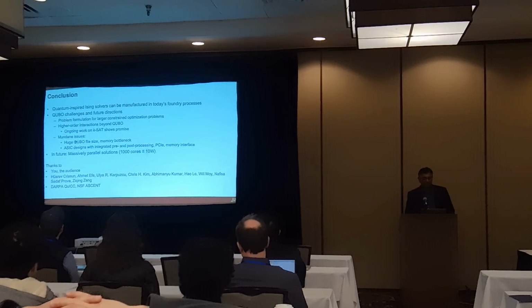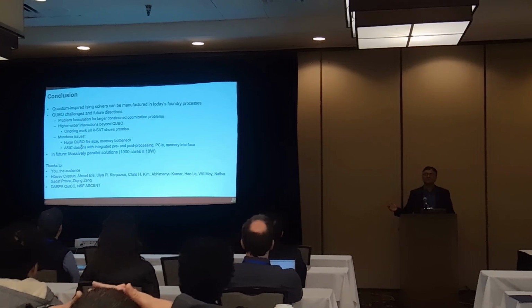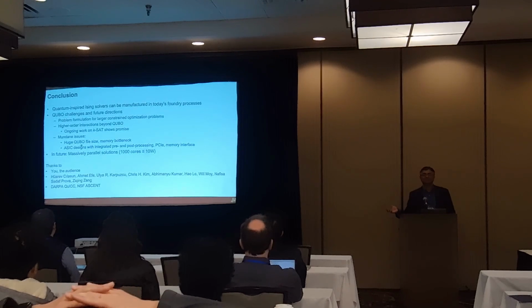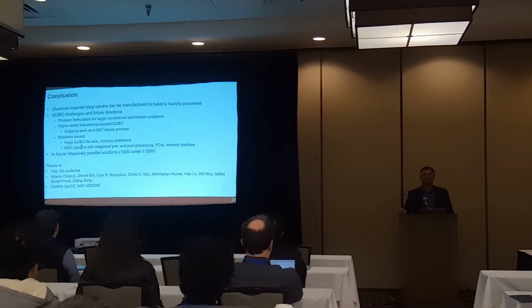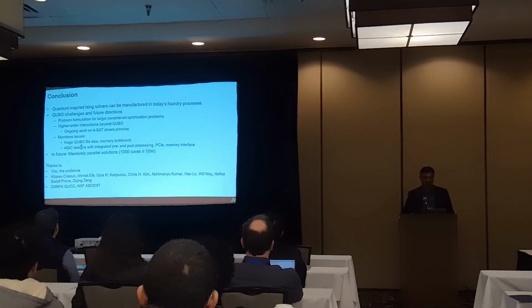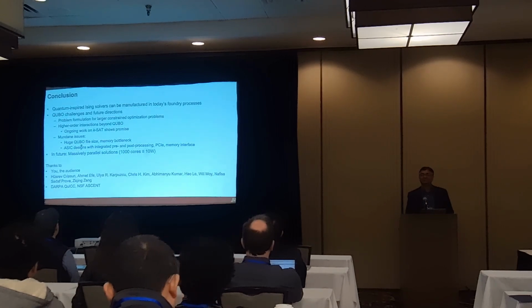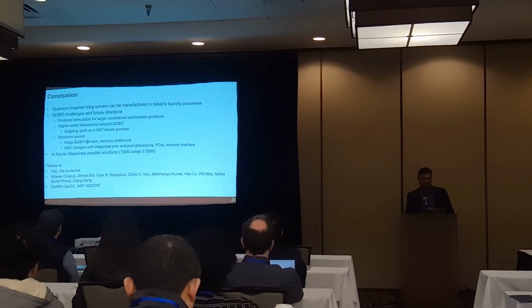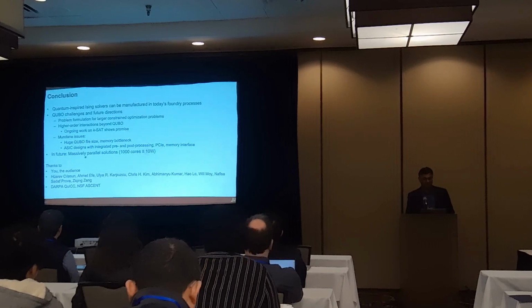There are a lot of mundane issues when you're building hardware. So you have to deal with the file size. You need to bring data onto the chip. How do you do that? You need to worry about how you're going to get, for example, a connection to PCIe, how you're going to get an AXI connection. So, in many cases, instead of buying IP to do that, you just buy a small FPGA, and it comes with this IP on it, and it's relatively inexpensive. So, there are creative solutions like that that are very mundane, but they're required to make things work correctly.